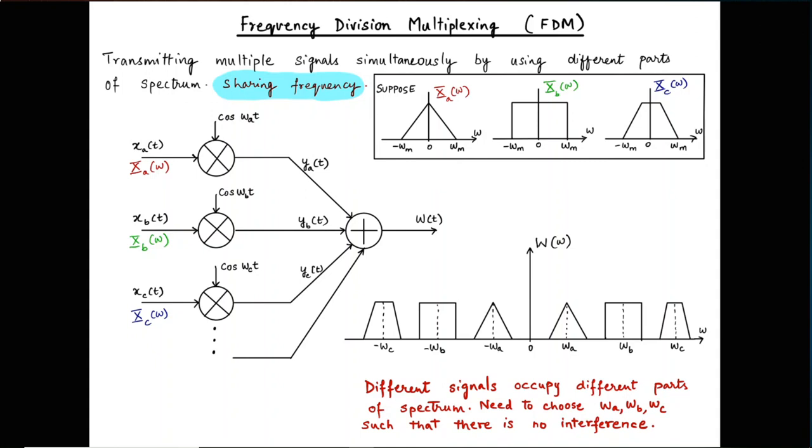So we can share the resource of time. User 1 speaks, after that user 2 speaks, and then after that user 3 speaks, and so on. That's time division multiplexing. There is space division multiplexing. There is phase multiplexing. There is also multiplexing we could do in power resource. But over here, we are focusing on the frequency division multiplexing aspect. So how can I share the resource of frequency? Can I use multiple resources, multiple channels, and can I spread them out in the spectrum?